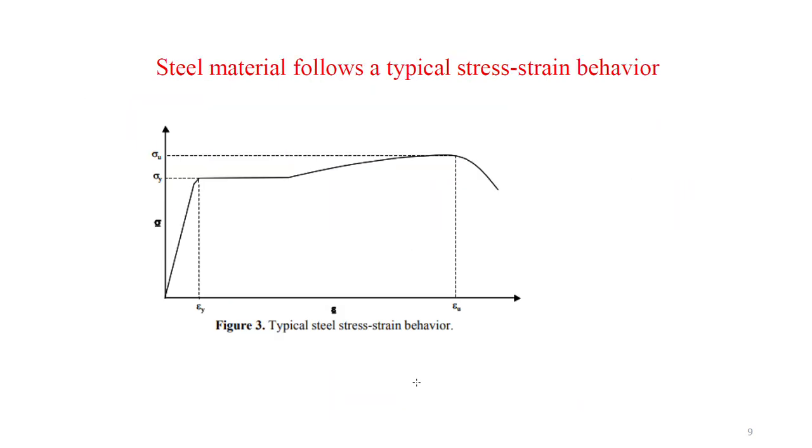And as we know, in the stress diagram of mild steel, up to the elastic limit, stress is directly proportional to strain as per Hooke's law, and it obeys Hooke's law. After that, it reaches its maximum limit with the highest amount of ductility. You can see the highest amount of deformation, in terms of strain. You can see maximum strain, which is obtained at the maximum stress, the ultimate stress.